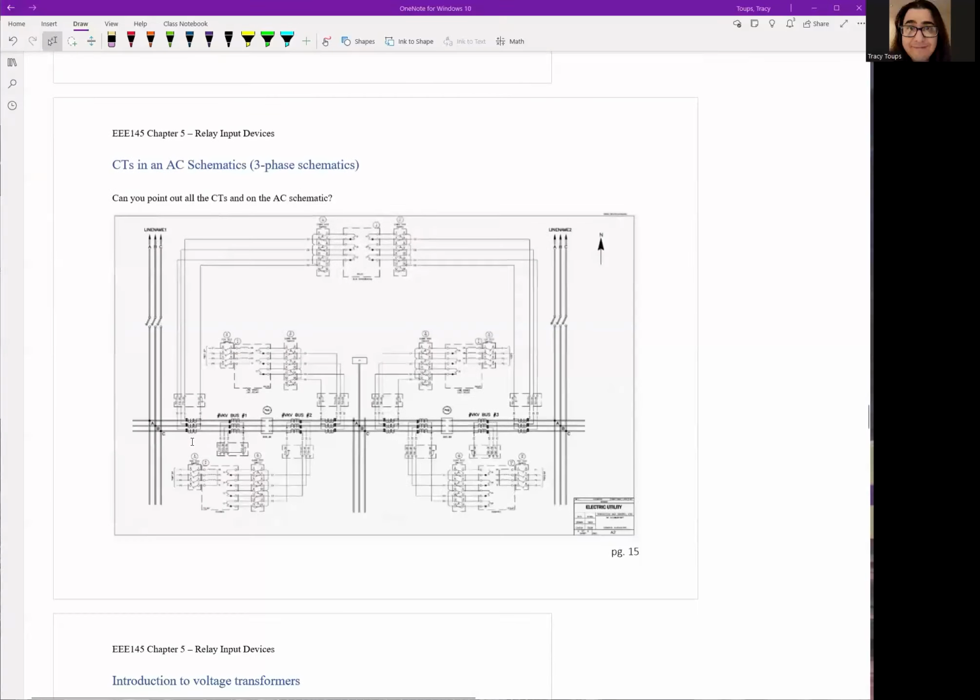Okay. Real quick, I want to put a 3-line diagram in front of you just to say, hey, if I see this, where the CT is, because in an interview, one very common tactic is they'll give you a diagram and say, tell me what you know about this. And at least I want you to know where all the relays are. Where are all the CTs? The easiest way is the bold 3 lines are typically the main power line. So you see ABC up here, ABC. The bolded lines, these are your wires, your phases. Okay. This is your current carrying wires.